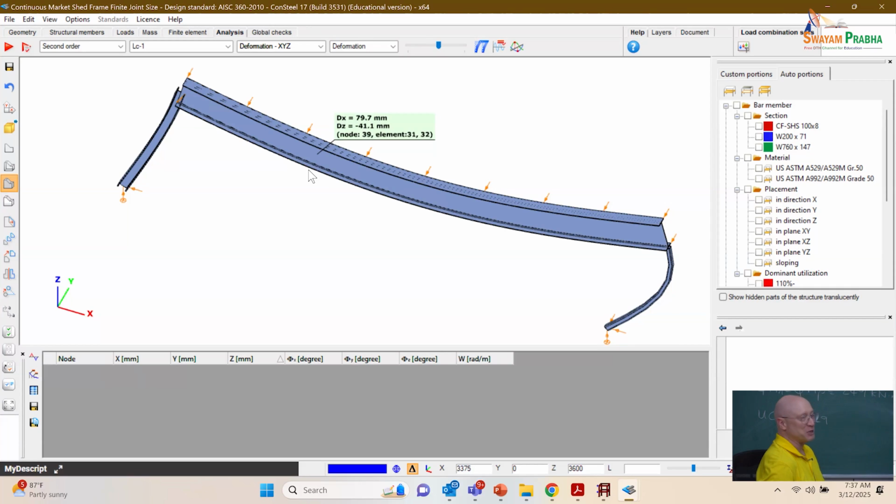But this sort of situation does come up in practice in various ways, where you have something, usually something relatively small, that's starting to get beat around by the rest of the structure. So again, in structural stability, we don't necessarily increase strength when we increase continuity or when we increase material. Change the idealization.